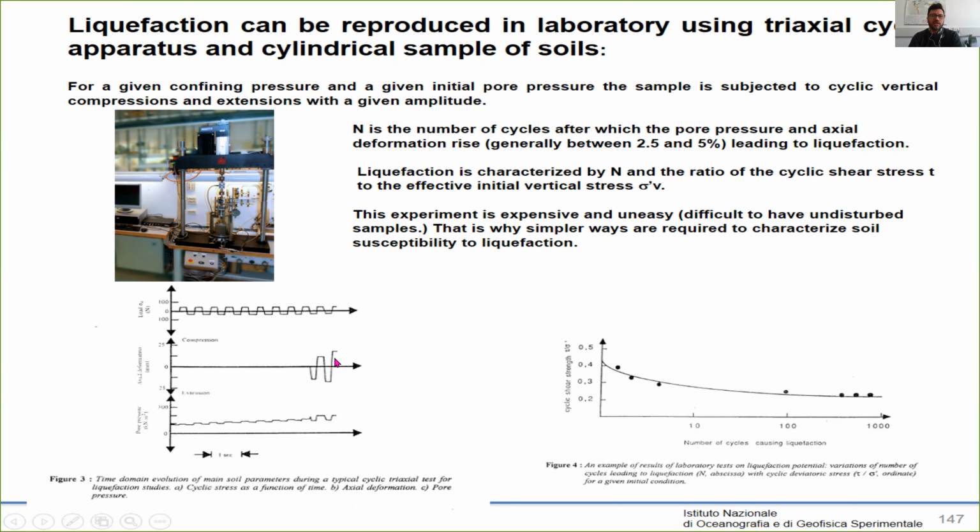And before that, the actual deformation is rising. So it's not only important for the liquefaction, the amplitude of a shaking, but it's also important the duration of a shaking. So how many cycles is the sample or the ground undergoing before it's reaching liquefaction? So this is the standard method that is used a lot in geotechnical analysis.